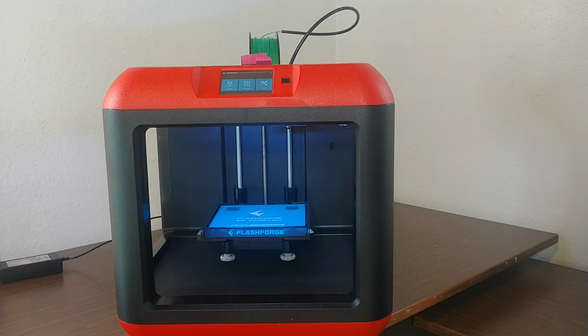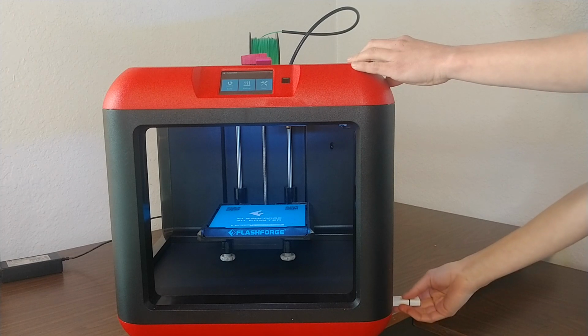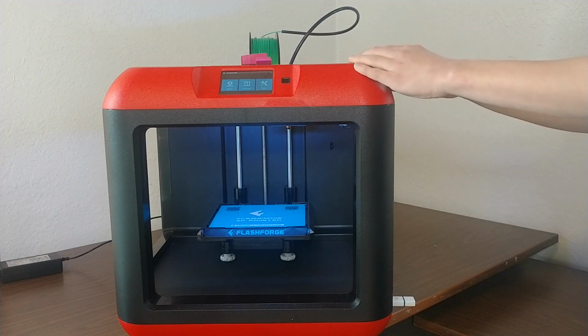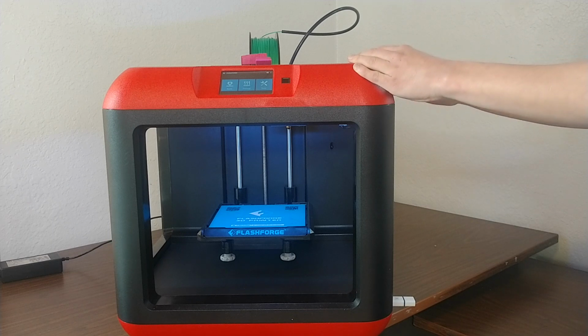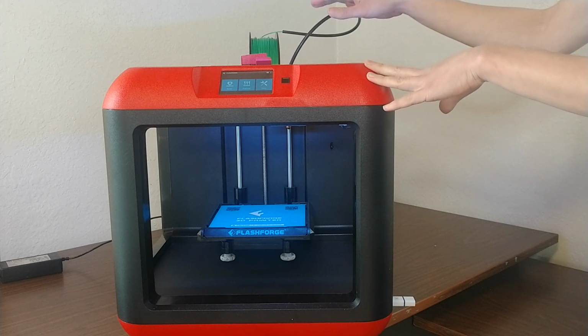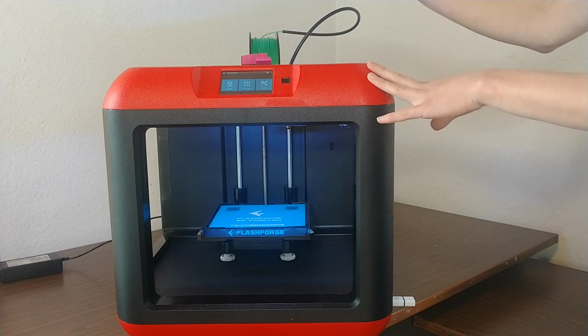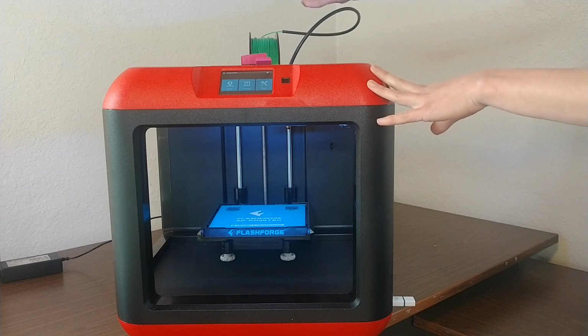Right now that I have my G-code file, I'm ready to print. So I'm going to plug my USB into the FlashForge Finder here, which is one of several ways to transfer a print job to this machine. And it's important to note that my printer here is ready to print. So it's powered on and it's loaded with the filament type of my choice. And this filament should match the filament type I selected earlier in my print settings, which in this case was PLA, and this is PLA filament.